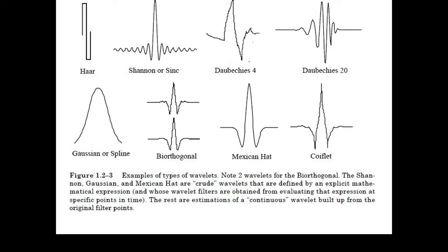Among these, for the analysis of ECG signals, Daubechies series wavelets are usually used, and mainly the dB4 wavelet. In short, Daubechies wavelets are represented as dB. So dB4 wavelets are usually used for the analysis of ECG signals.